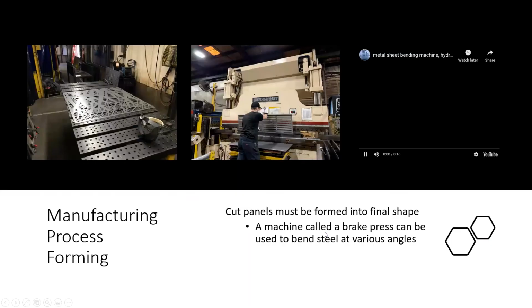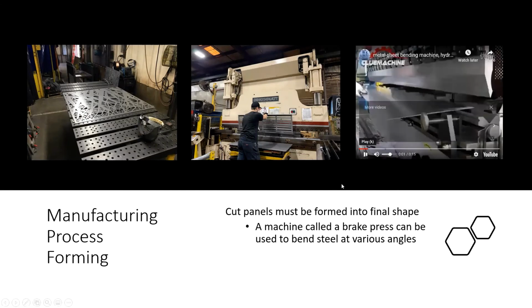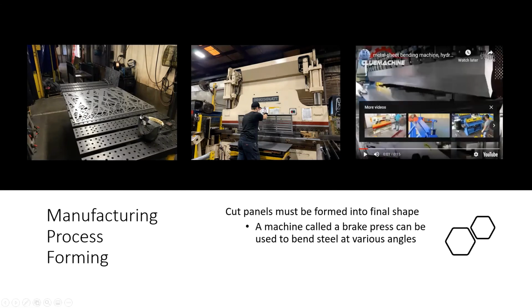Okay, so what we're looking at there is the sanding process. Immediately coming out of some type of subtractive manufacturing method, you're going to have little tabs or little deflections, whatever the case is. It's not going to be perfect. So you need to sand all that down, especially since it's going into a customer space of some kind. You want to make sure there are no sharp edges. So most of these things, wherever the cutting actually occurred, are going to be sanded down, so that you're removing all of those different pieces.